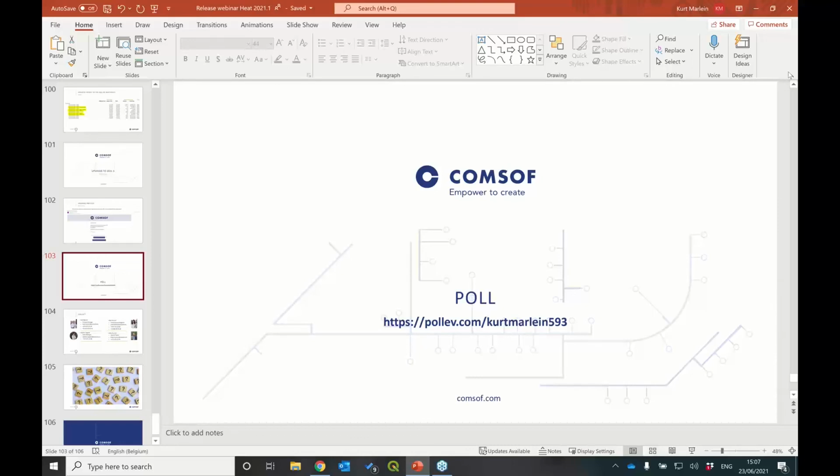Yeah, the heat loss is currently calculated based on the formulas in the EN 13941 standard. And now with the buffering, the principle remains the same. We have the heat transfer running through the pipes. We still apply the same formulas, which are actually part of our training. And as indicated, the additional losses that we will have now is the buffer tank storage throughout the year, throughout the day, which is given by a certain percentage.